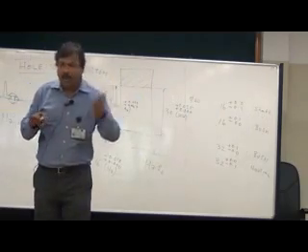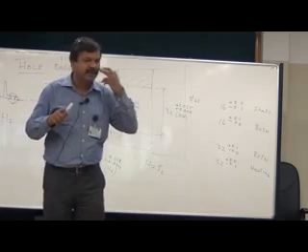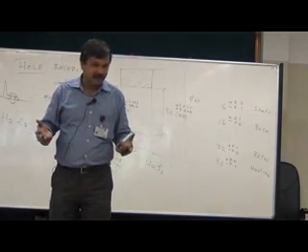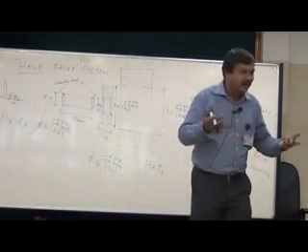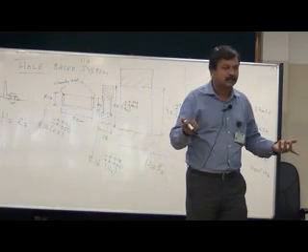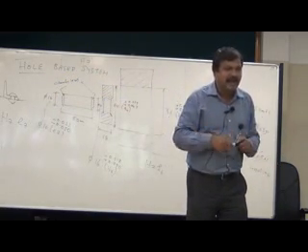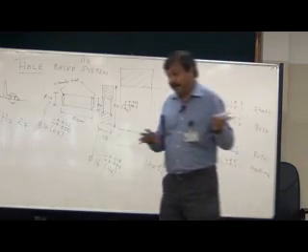Now, what is the solution? Why does underburning or overburning of bricks take place? Can you put yourself in that situation and analyze why underburning must happen at all? Everything is put inside the same furnace. Why should there be underburning at certain parts? It's not uniformly exposed. Fine.